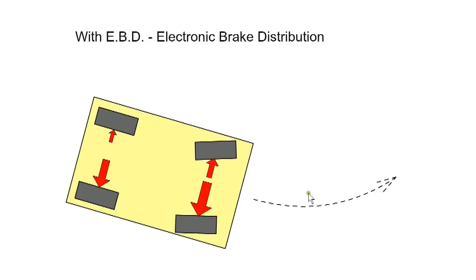the steering wheel position sensor to determine the intended path of the driver. This data is processed by the ECU to determine if some of the wheels are lightly loaded. The braking force is reduced on the lightly loaded wheels and increased on wheels which are braking most effectively. In effect, the EBD activates before an ABS situation arises and helps to improve stability and reduce stopping distance.